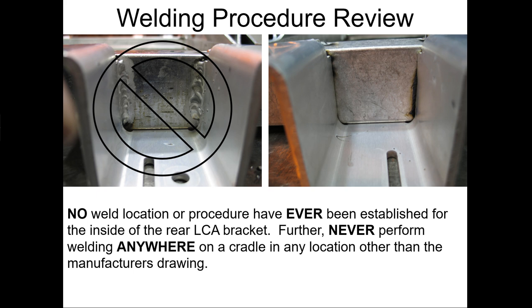This was another project I was on one time with an LCA bracket. I just want to point out, and I know I've done this a bunch of times, weld does not go anywhere that weld does not call out. Your border sample, your sample on the shop floor that looks at your part, gives you all the things we want it to be, and we'll be looking after those locations. Anything else cannot get out of the plant, should go into containment, and start containment protocols immediately if you ever see anything like this at all. Even on one part, don't let it get out.